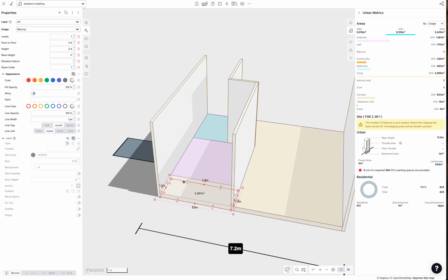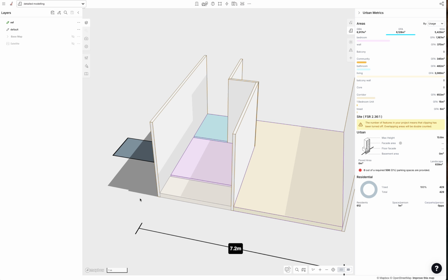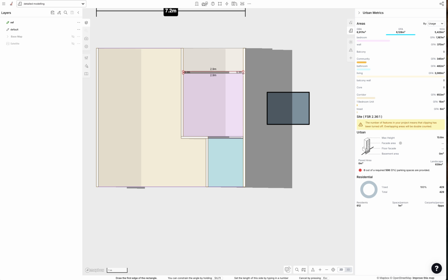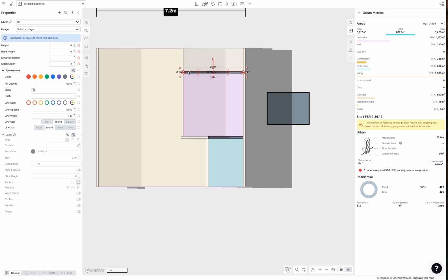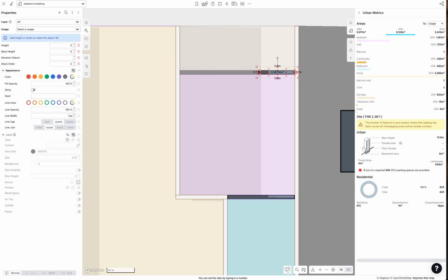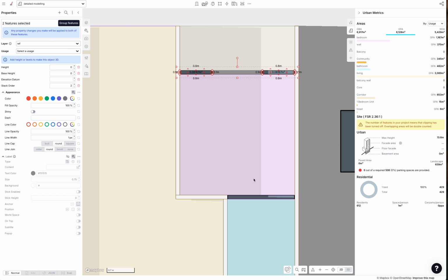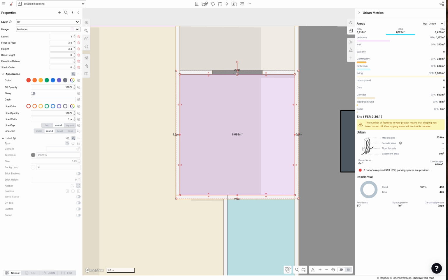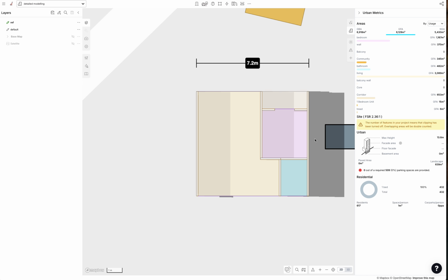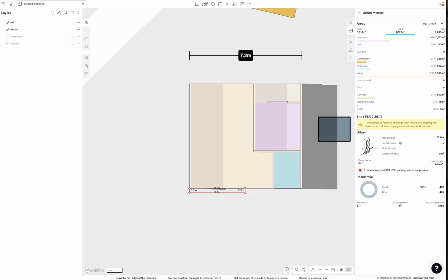And I'm going to pull this balcony out 0.1, pull this bathroom back 0.1, and then holding that snap and that rectangle, finish those walls off. And this one, I'm actually going to just pull back like this and then pull like this. The reason for that is the indication of a door. And then I'm going to use that Y. And now I'll pull this bedroom like this out. Close that gap. And the last wall we need is this wall over here.